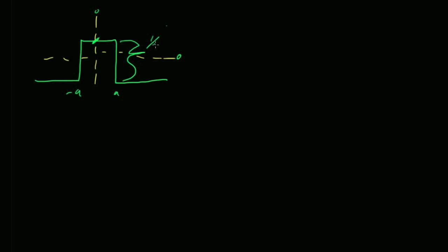So just like the Fourier series, the magnitude of your Fourier transform doesn't change. What's the only thing that's different? DC offset. And DC offset is energy at what frequency? 0. So how is my plot going to change? It's going to go down by how much? It depends on the value of A, right? If the whole thing is 1 over 2A, it went down by half of that, right? So 1 over 4A. So what you would do in that situation is draw, there'd be a discontinuity here, and this would be 1 minus 1 over 4A.